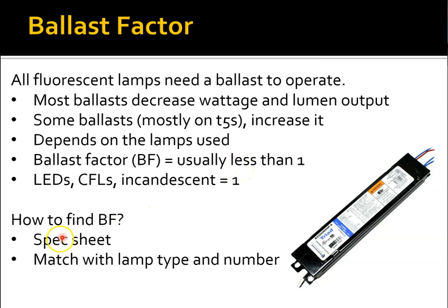Ideally, what you want to do is find the spec sheet of the ballast, match it up with your lamp, and then you can figure out the ballast factor. And just so you know, if you're dealing with LEDs, they don't use a ballast, they use a driver. Ballast factor of 1. CFLs, incandescent, ballast factor of 1. So you don't have to worry about ballast factor for those. So normally we want to try to find a spec sheet.